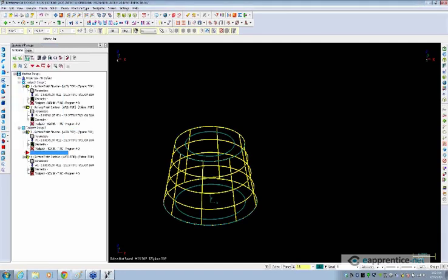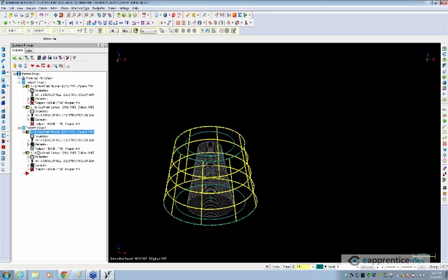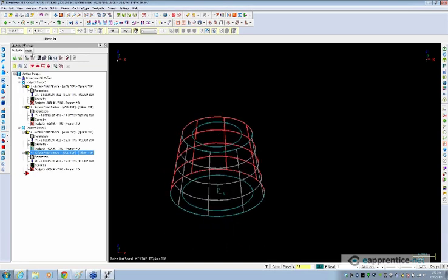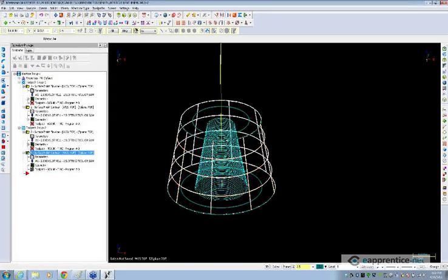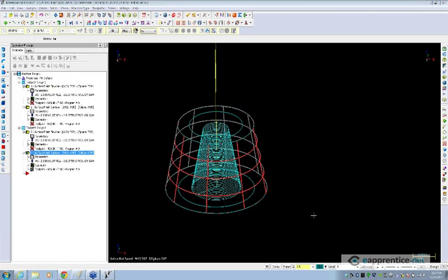Surface finish contour doesn't care. So I'll regenerate my surface finish flow line, and we'll select surface finish contour. Now again, my normal's pointed to the inside. If I go in, change normal, flip it to the outside, and then I take surface finish contour and regenerate it, it simply won't matter. It's still going to generate a gouge-free toolpath even though we're cutting the back side of the normal of the surface, because the cutting itself is simply controlled by the containment boundary. The containment boundary tells it, I only want to generate motion inside of this circle, and so that's where it's going to do its cutting. But that was a great question. Thanks for the question there, Clifford.